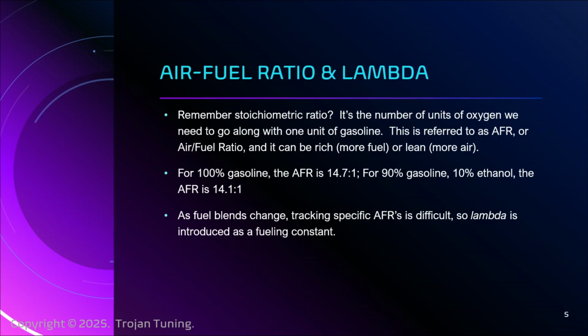Everybody's talking about E85, and you know they should be. If you go to an E85 pump in town, you are not going to be getting 85% ethanol out of that pump. It never happens. The law says it has to be at least 50%, and it can be up to 85%. I think the highest that people have seen in the field is something like 79%. That would be a golden pump. If you know about it, maybe you want to keep it quiet, or maybe you want to tell everybody, because that would be a magical pump, right? But the ethanol content will vary from pump to pump, day to day.